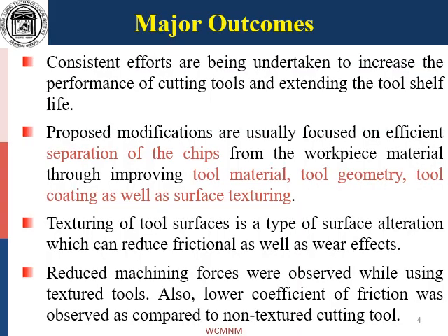I have listed the outcomes of some of the studies here. As can be seen, texturing helps reduce the resultant friction and wear generated, thereby extending the operational life of a tool. The machining forces were found to be less impactful on a textured tool as compared to a non-textured tool.